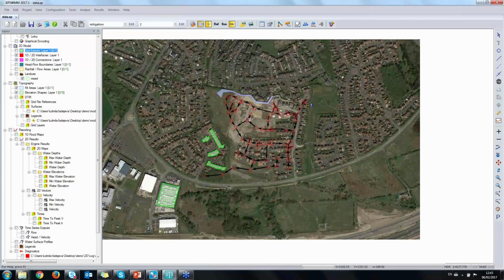So we take our MicroDrainage modeling, take a bigger area, and take an aerial picture. If we want to introduce some buildings and check if they're flooding, we can quickly create channels and items, run different scenarios for different rainfalls, and finally export all this data in GIS format, and we can submit it to either